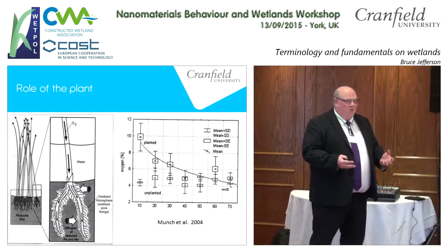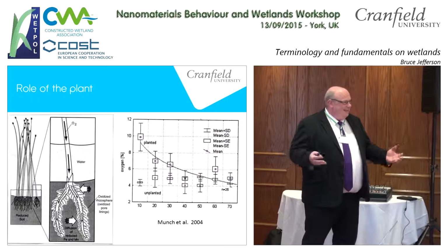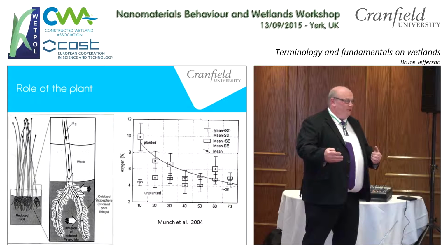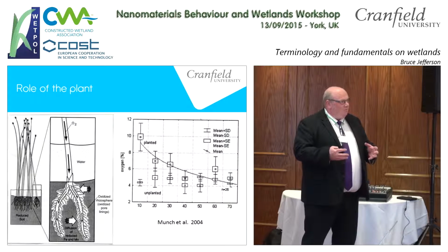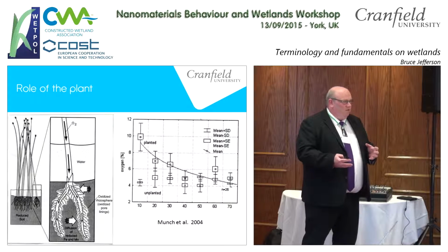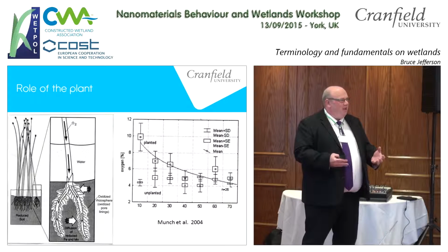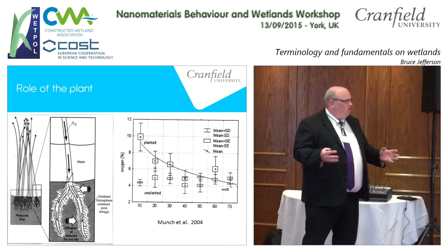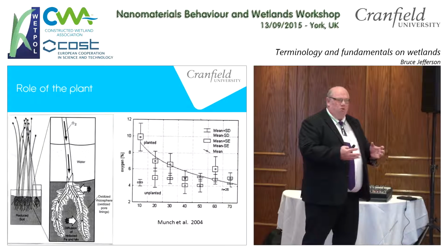Now, it's not enough to aerate a wetland, and so it's not going to drive aerobic biological processes if I'm trying to treat sewage, but it is there as part of the plant's protection mechanism. So when I'm looking at uptake of metals into plants, there is already an aerobic protection mechanism there, so when I change certain aspects of that, they're still going to exist.